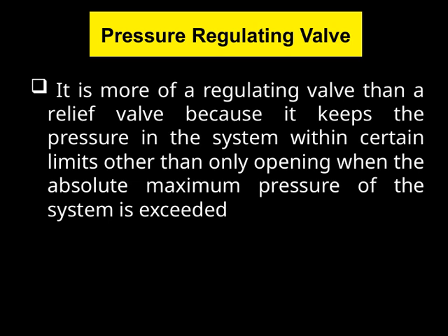This is especially important in applications where consistent pressure is critical for performance or safety. So, in essence, while relief valves are like safety nets that only act in emergencies, pressure-regulating valves are more like control devices that manage the pressure continuously during normal operation. This concept ties into our overall discussion on maintaining system integrity and safety.